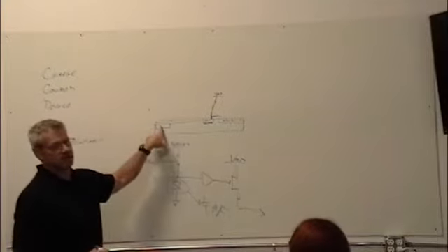And then if you imagine, oh well, C equals Q over V, but remember AC current is I = C dV/dt, and now I'm shifting 17 volts in 25 nanoseconds. Those are not milliseconds, nanoseconds. That's a really big number. If I look at the gates on some of these, I could be looking at C's of approximately 2,000 picofarads.